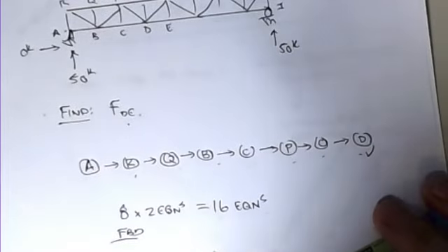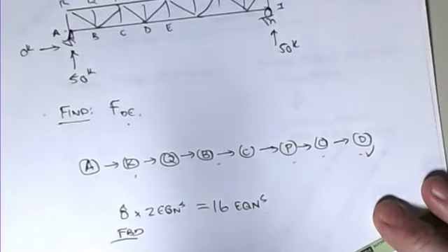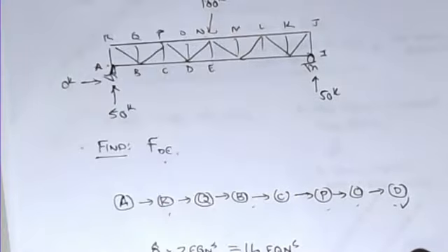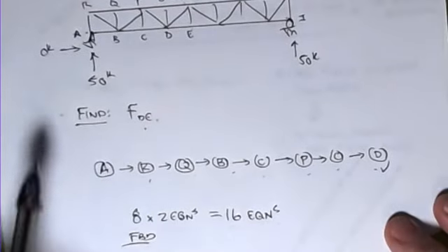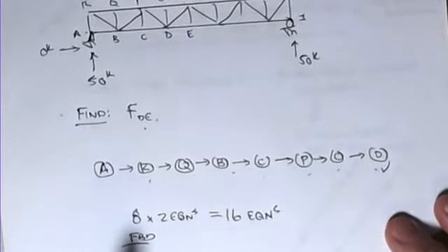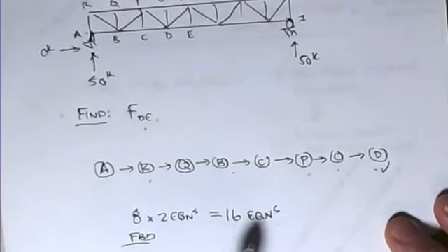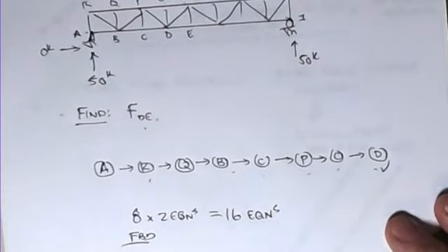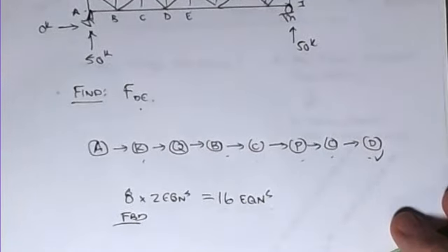So the method of joints is very simple and very straightforward. It's two equations per free body diagram, and it's pretty handy if I'm trying to find something in the first couple of steps, or if the structure is fairly simple. But if you're trying to get out into the middle of one of these really long trusses, that's a problem. And so we need a better way. That will lead us into our next discussion, which will be known as the method of sections. So if you guys will stay tuned for that one, I'll work us through that as well.